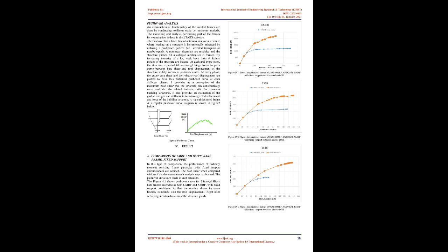A more realistic performance of SMRF and OMRF buildings necessitates modeling the stiffness along with the strength of the infill walls. The variations in the kind of infill walls used in Indian construction are considerable. Based on the modulus of elasticity and the strength, they could be classified as weak or strong. The two extreme cases of infill walls, weak and strong, are considered by modeling the stiffness as well as strength of infill walls as accurately as possible in the current study. The behavior of structures depends on the kind of soils.